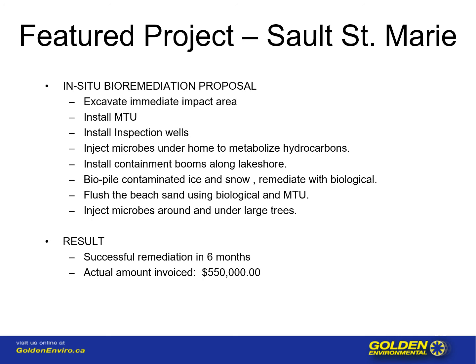Number one, to establish hydraulic containment, so the groundwater flow from the contaminated area did not continue to migrate into the lake. Second of all, we took the contaminated snow, melted it, and put it through the mobile treatment unit. The result was successful remediation in 6 months, and the actual amount invoiced was $550,000.